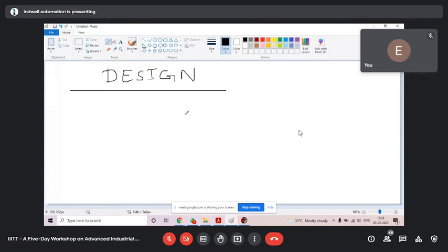So in tag, what is this tag? You have designed a switch. You double click. You have to give some address. In HMI, you have given X0, X1, Y0, D0, T0. In SCADA software, it won't accept X0, X1, X2, X3 like that.